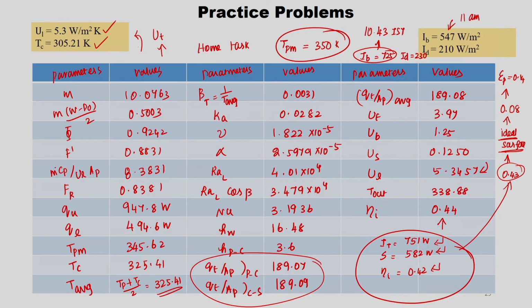If you put two or more covers, you can check the losses, because the cover system's function is to protect the plate from the environment, to allow the solar radiation to be absorbed on the absorber plate, and it should emit less. It should prevent convection and radiation losses. So, how many glass covers would be required?